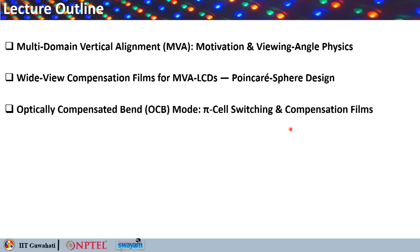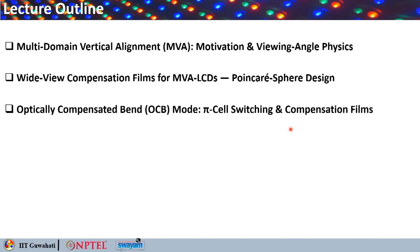So here's the lecture outline. The lecture has three parts. First, the multi-domain vertical alignment, MVA: the motivation for splitting each pixel into 4 different domains and the resulting viewing angle physics will be discussed. Second, we will talk about the wide view compensation films for MVA LCDs that are used to further widen the MVA's contrast cone, designed using the Poincaré sphere graphical method.